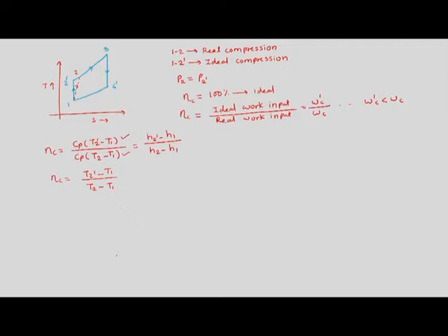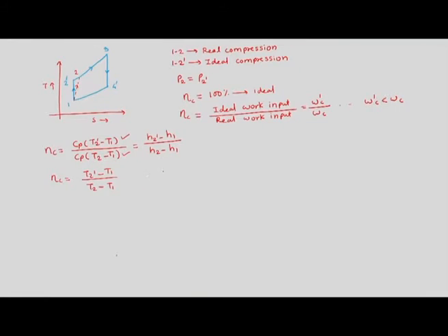When we deal with the examples, we will understand that compressor efficiency is a known parameter for us. In parallel, we also know that pressure ratio is a known parameter for a compressor. So pressure ratio is known, compressor efficiency is known, and we also know the inlet conditions of the compressor. So practically what we would know is compressor efficiency, pressure ratio, gamma and T1, or P1. These things would be known to us. Having these known, our objective here is to find out what T2 is.